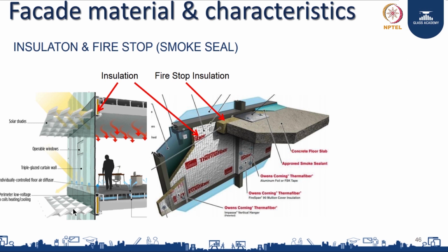Commonly in all buildings, you do not use a fire stop because your system is not fire rated. Unless your system is fire rated, there are hourly fire rated systems like 1 hour, 2 hour, 3 hour, whatever. But in any common building, mainly they use non-fire rated walls, i.e. your wall cannot withstand any rating. So, either they are half an hour or less or even 5 minutes. So, what you are going to do between the slab, you should call that first a smoke seal.